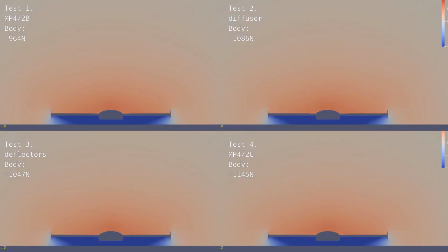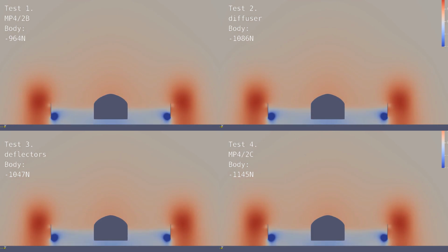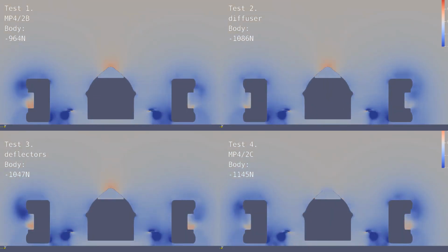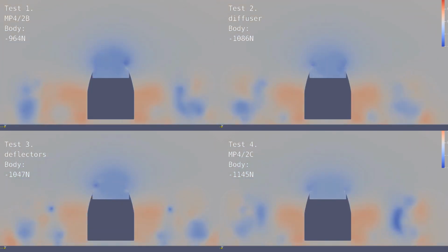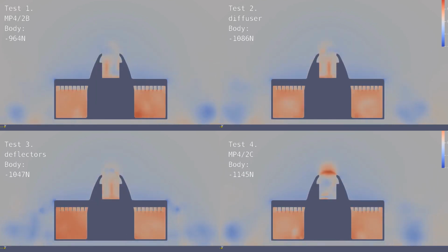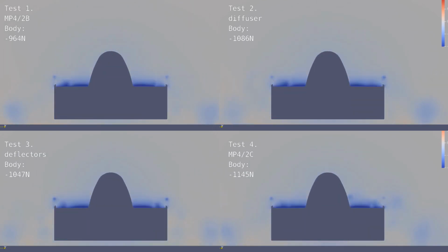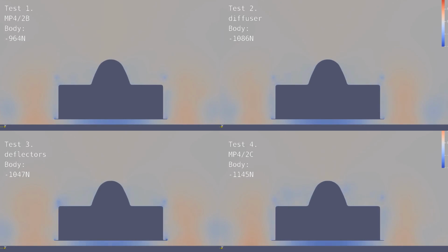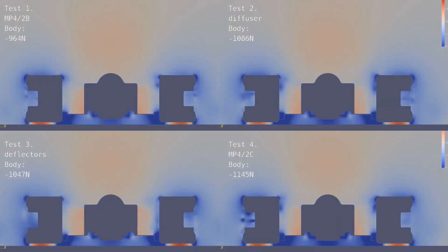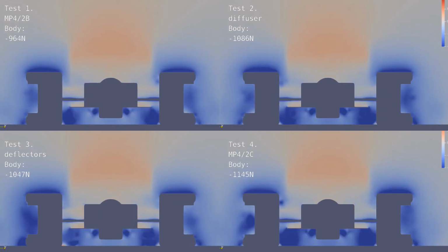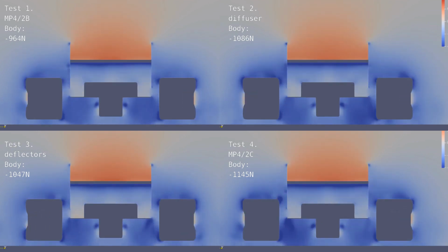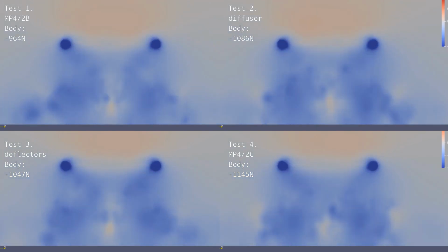Mentioned previously, there appears to be discontinuity in the flow pressure regions in the diffuser. I paused the animation at the rear axle to highlight this and how it differs with model configuration. The lesser blue regions mean their air isn't accelerating as much. As a basic rule for diffusers, the air should continue to accelerate through the diffuser. It's its primary purpose.